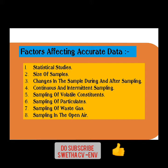Along with that, the gas stream has to be in the same speed and same direction. It should not go in the opposite way. If it goes in the opposite way, then everything will be disturbed. Okay friends, so these were the conditions for sampling of particulates. One, in isokinetic conditions, input equals output, same speed and same direction.